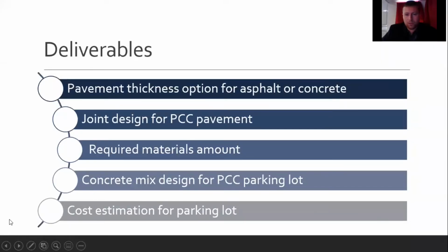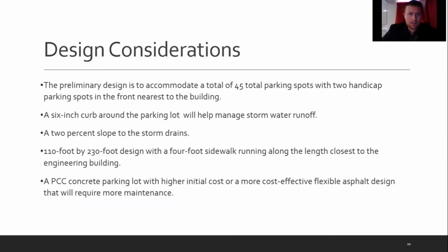The deliverables for this project will be showing different pavement thickness options for asphalt and for concrete. It'll also show a joint design for the PCC pavement. It'll also have required material amounts along with the concrete mix design for the PCC parking lot, and we'll have cost estimations for both.